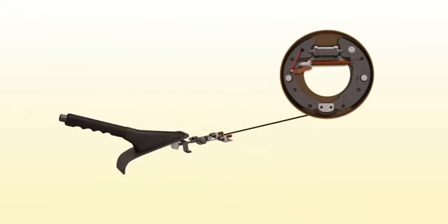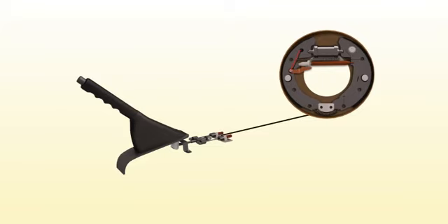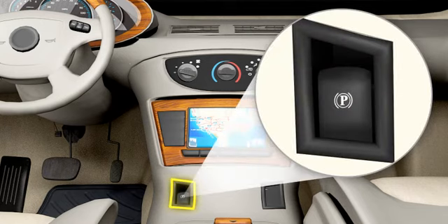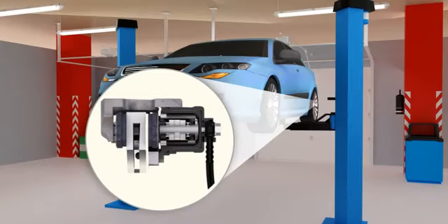The parking brake is a mechanical or electromechanical system that locks the rear brakes once the vehicle is parked. Until recently, most vehicles had a completely mechanical system, using steel cables to connect the parking brake handle or pedal to the rear brakes. Many newer models use electronic parking brakes. These systems use electric motors to pull the cables or to activate a parking brake mechanism in the rear disc brake calipers.